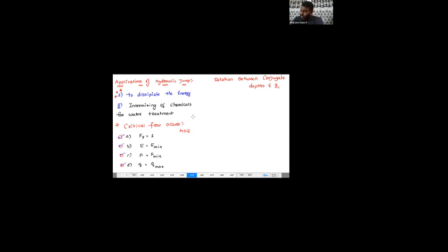So here, when Froude number is equal to 1, and E becomes E minimum for a given discharge, F is equal to F minimum for a given discharge, Q is equal to Q maximum for a given specific energy and specific force. Keep that in your mind.